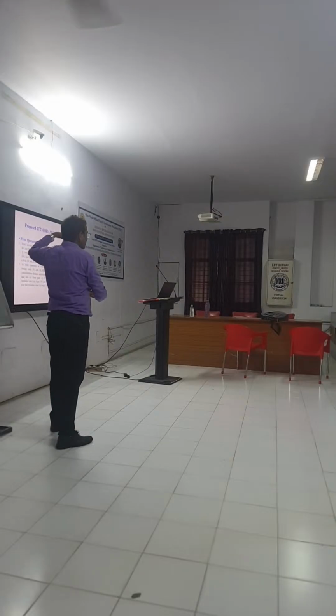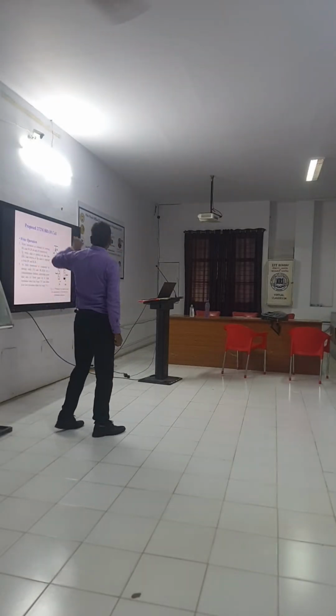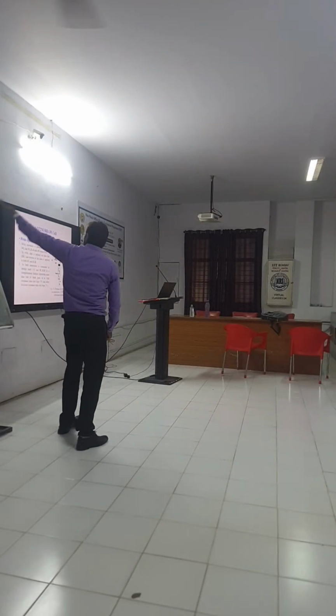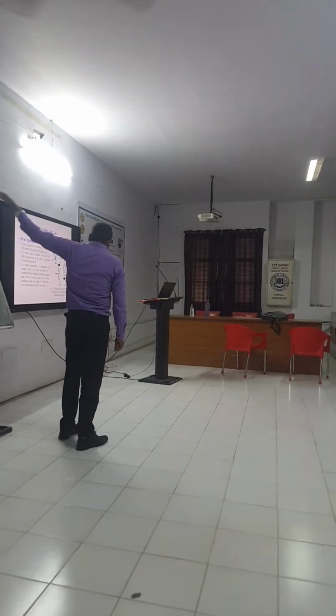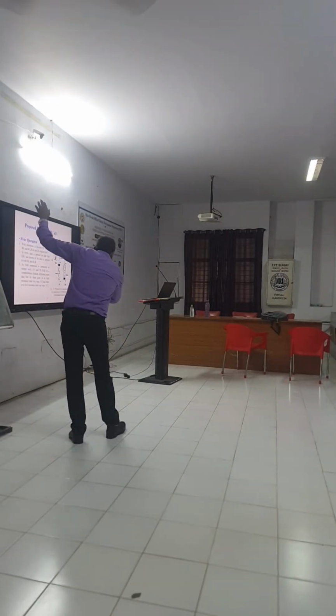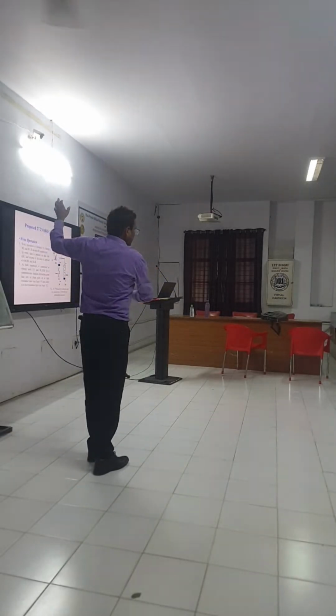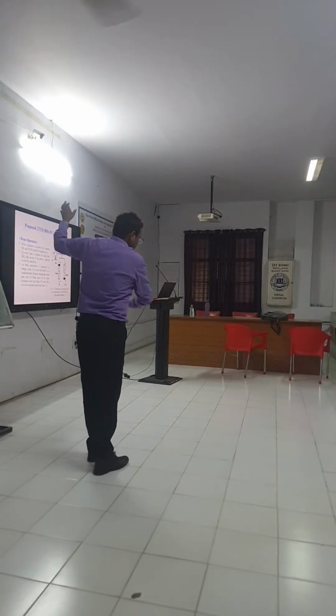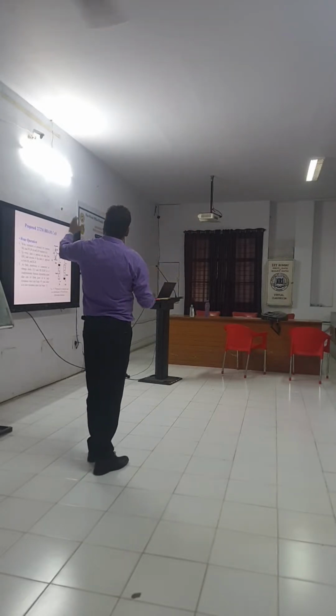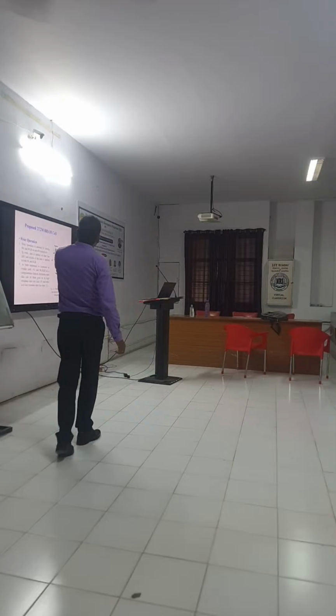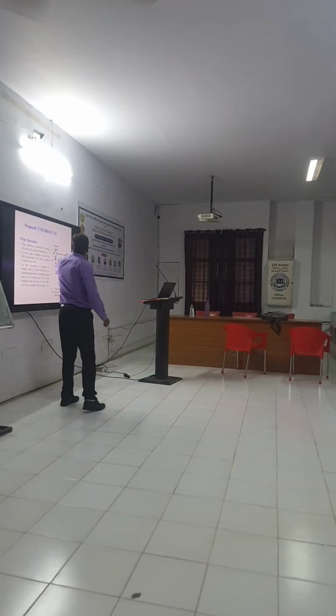If you know the memory architecture, the external circuit on the left side is the write driver, the row decoder circuit is there, and down below is the column decoder. In the column decoder, the write driver circuit, sense amplifier circuit, and pre-charge circuit are there.